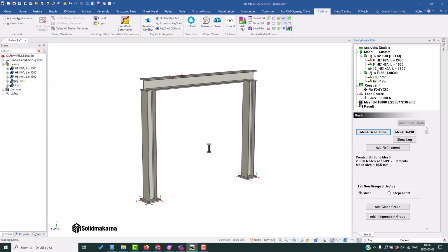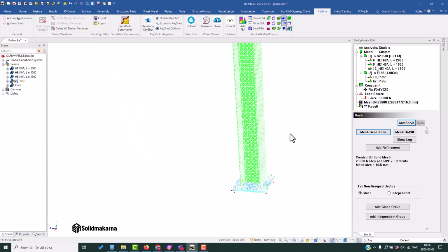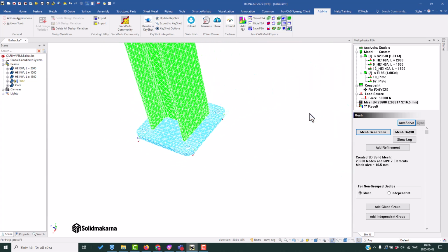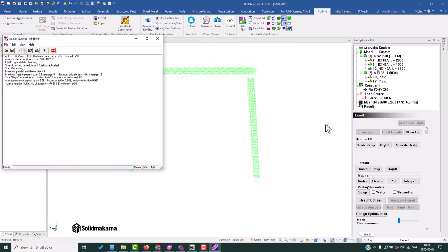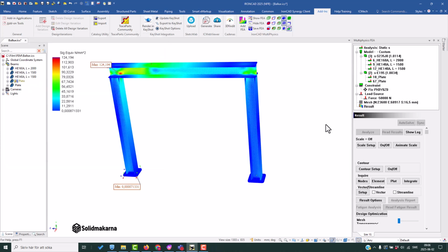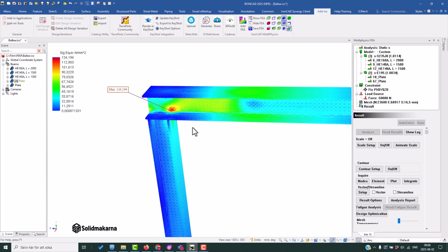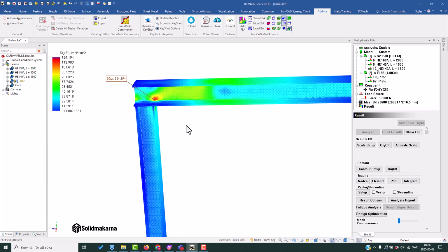It can be the case that you see a quite different result when I now hit AutoSolve. You see here that it's a bit finer mesh than before. Every distance is a bit closer between the nodes. And now I click on AutoSolve and it's calculating again. The stress here is 124. It's quite a big difference really. So it was good to make the finer mesh.